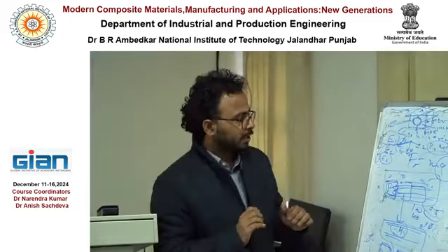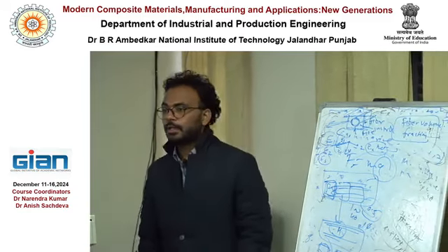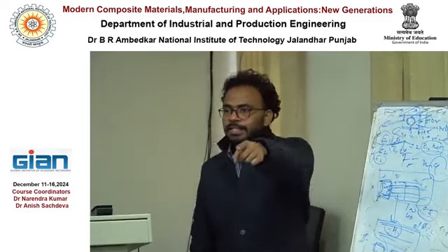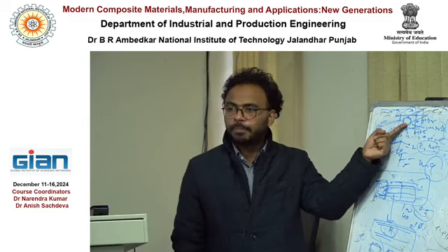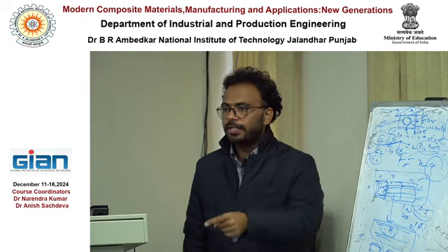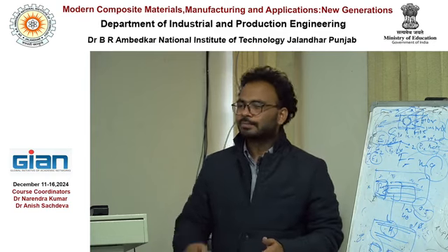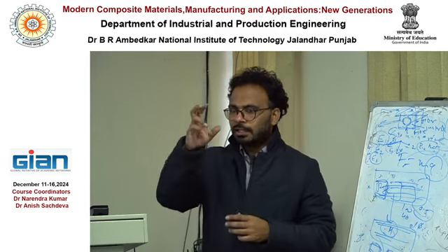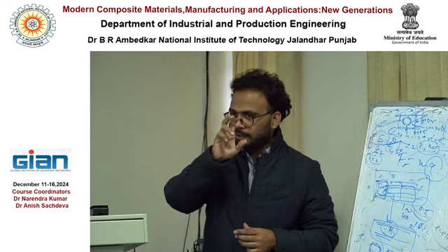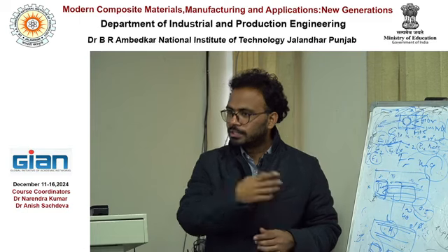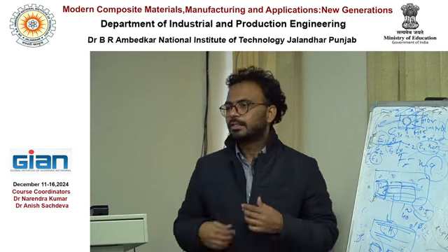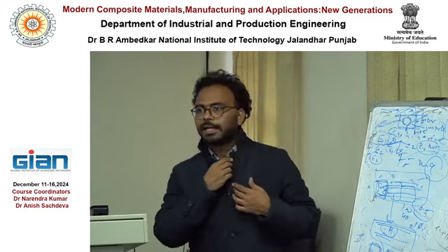Okay, so I think it's covered for you. You can vary this only. Suppose in his case he knows the fiber properties directly. For your case you need to change the properties by thickness. USDFLD you can use. Getting the point? With this very simple subroutine you can get the script. Just change your properties, put them in, and you know the subroutine installation. Install it, assign it, and run it. I think it's finished now.